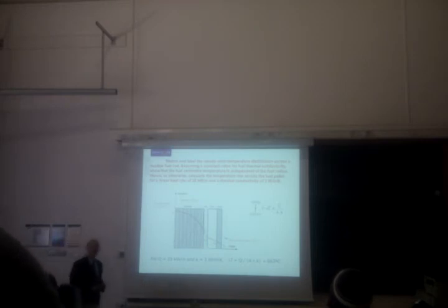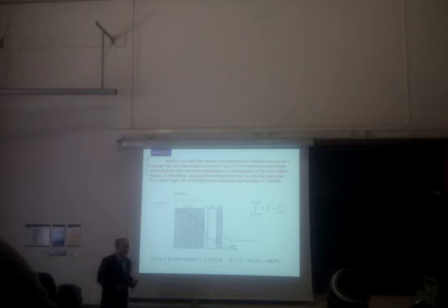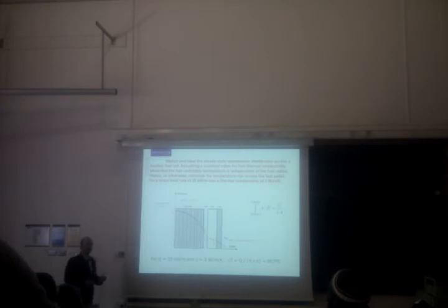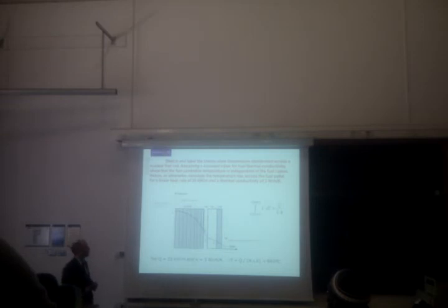What's in the gap? Gas, yeah. Do you remember which one? Helium, yeah, absolutely. Helium, for the most part, is in the gap. There's also a little bit of air because we don't vacuum it out before we manufacture the rods. So there's roughly an atmosphere, or 1 atmospheric pressure of air in there as well. But there's about 30 bar of helium, roughly.